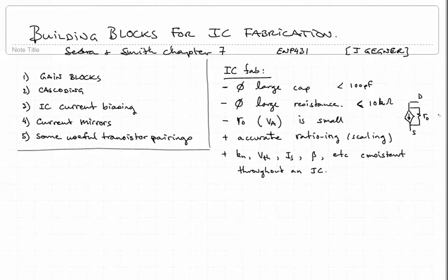What that means is that we can't ignore it like we have for most of our amplifier analysis so far. We just left it off, and usually the loading resistor, the collector side resistor or drain side resistor, was just the discrete resistance in series with the drain or the collector. Here that's not the case. You can't ignore RO. So there are going to be efforts to increase the effective RO, because without a large RO, you're going to limit the voltage gain that you can achieve.